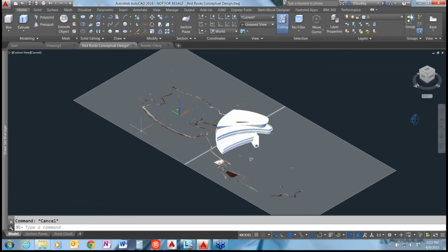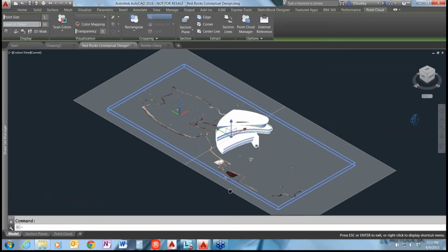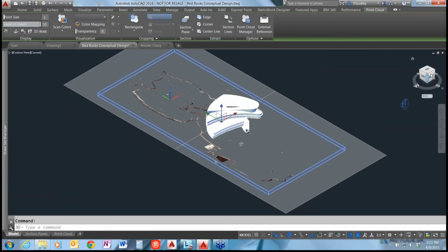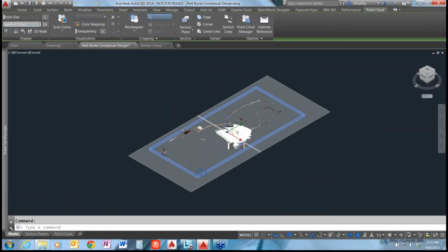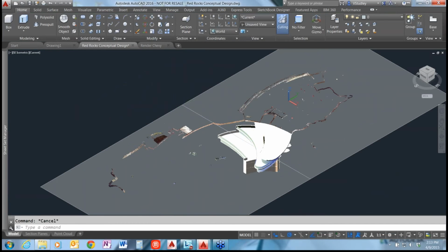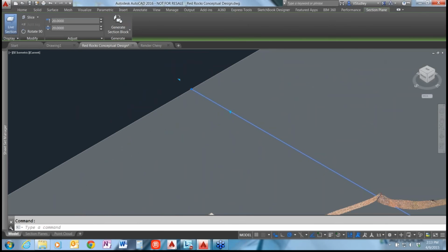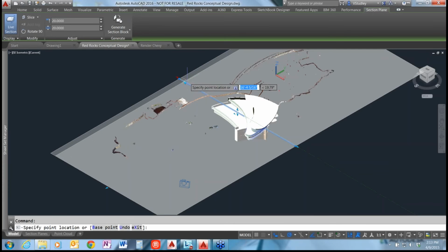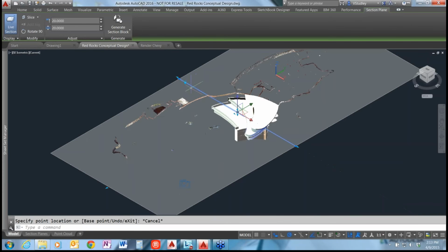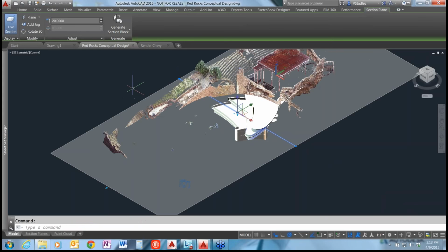Okay. All right. So there are also some grip enhancements that have been made. And I'm trying to find them here. Oh, I've selected it, there we go. So if you select the section plane and grab these grips, you can edit this dynamically right in the model. You can quickly flip this from a slice to a plane or a boundary or a volume section plane. So if we wanted to change it quickly, we can do so using that toggle.